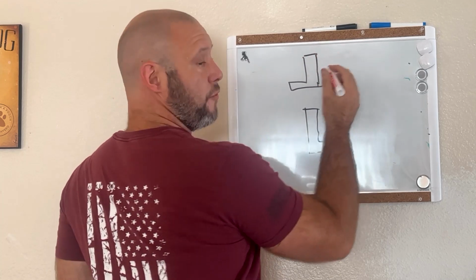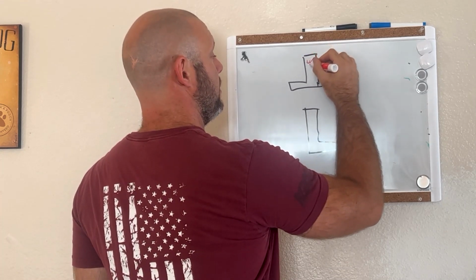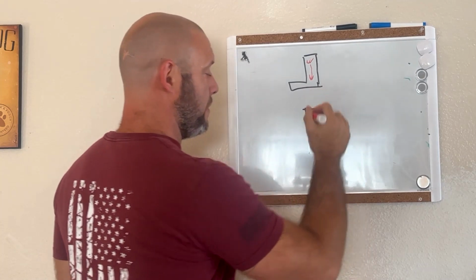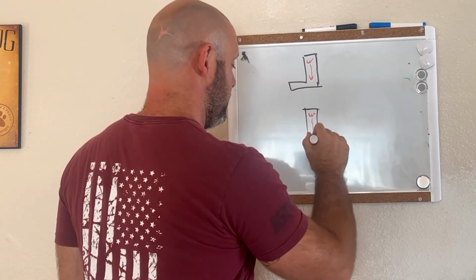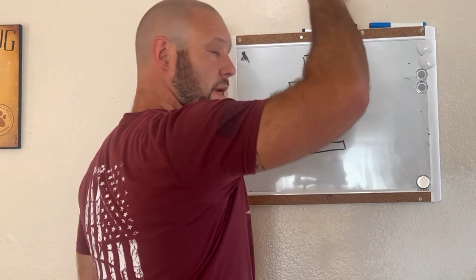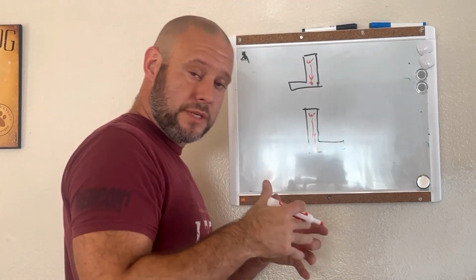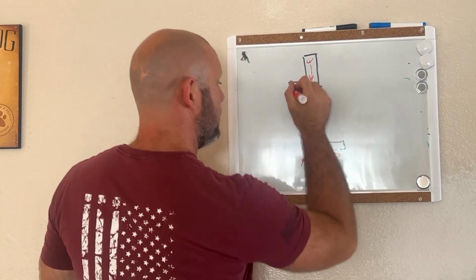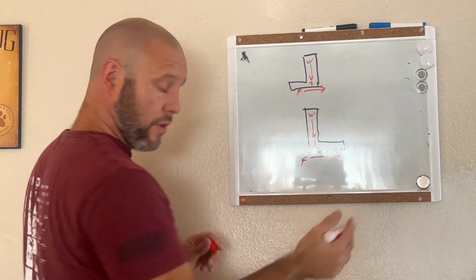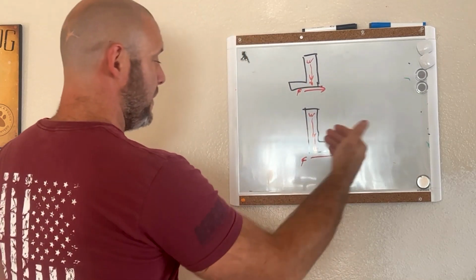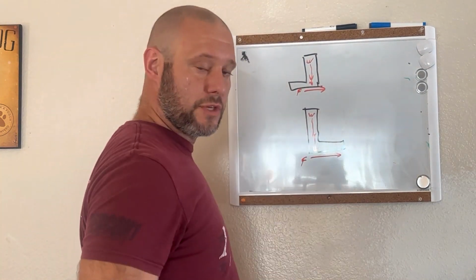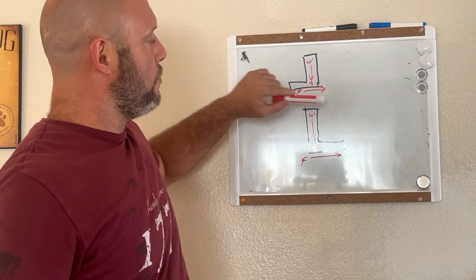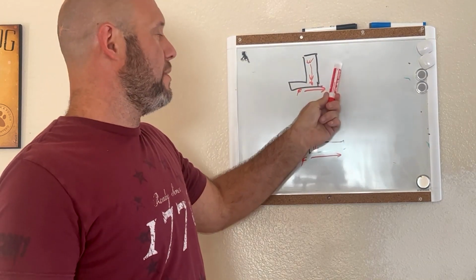First of all, the forces that you have to resist that strengthen it are the weight of the concrete, or the top of the retaining wall, all pushing down to the bottom of the retaining wall, right? So that's one of the forces that helps anchor this guy in place. The second force is your friction resistance, which we increase with the geomaterials down on the bottom, and that helps you prevent the sliding that you were experiencing, okay?